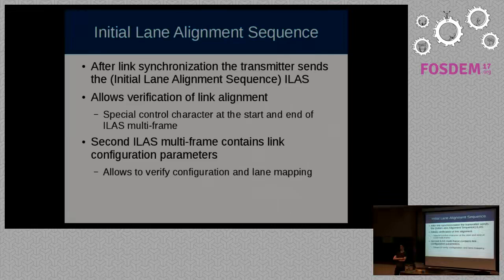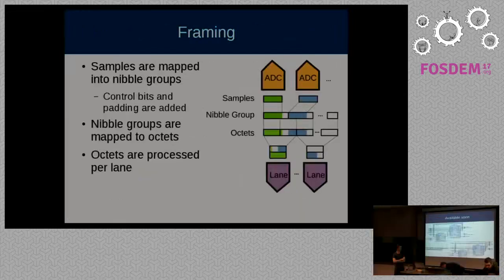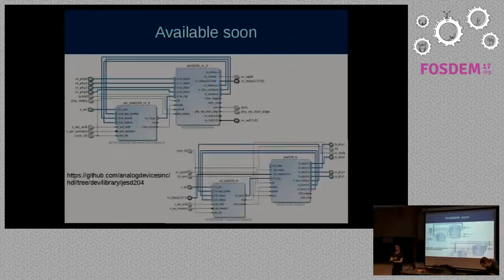Can the recovered clock from the deserializer be used to run the device, in the case of a DAC, rather than distributing the clock itself? Yes, it could be, but the standard explicitly forbids this. So the question is, can you use the recovered clock to run the device itself rather than distributing a separate clock to the device?